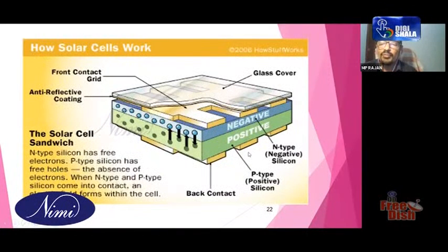So once again, to come to the actual construction, this is the negative region, this is the positive, this is the N-type semiconductor, this is the P-type semiconductor. On top is the metallic conductor, called metal fingers, and one anti-reflective coating is also given on top, because if light reflects and goes away, your intensity will decrease. So to retain the intensity, an anti-reflective coating is also provided.